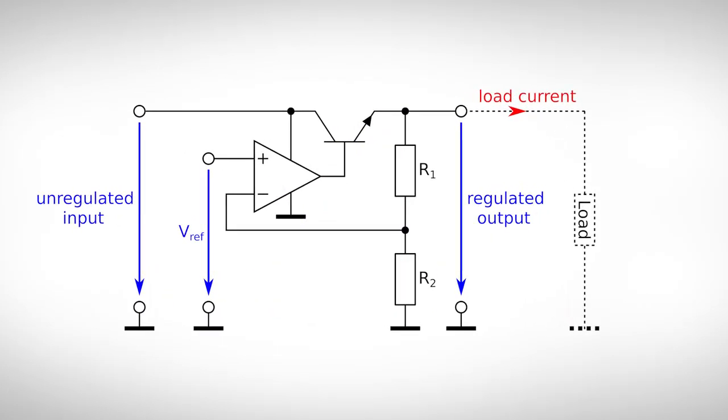The use of a Zener diode as reference voltage works quite well, but has some disadvantages, in particular for line regulation. Therefore, most voltage regulators are built with a control amplifier. The reference voltage for the amplifier can again be generated by a Zener diode. But in most common integrated regulators, this is usually done by a bandgap reference, which is much more accurate.